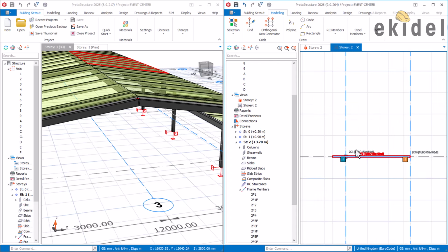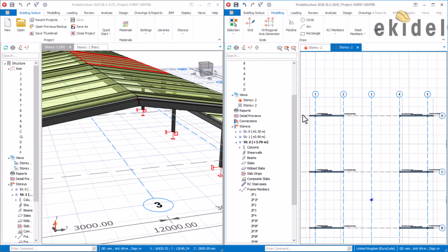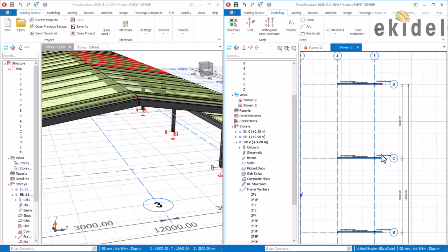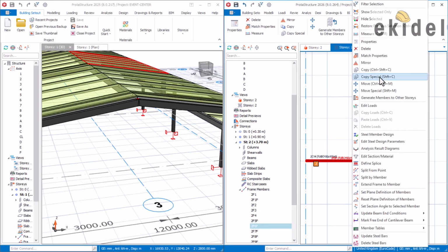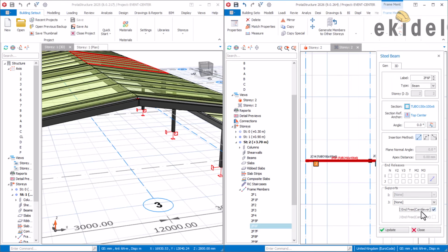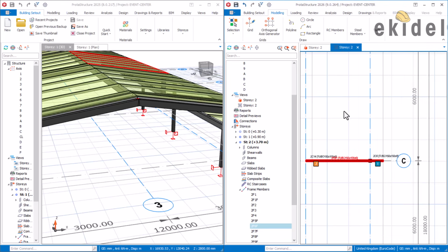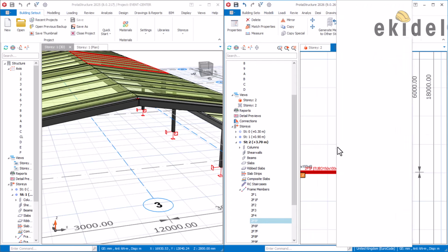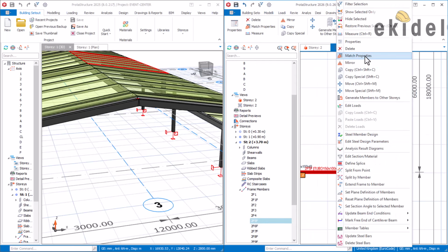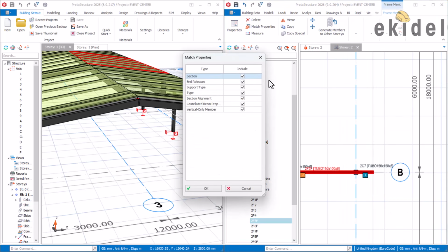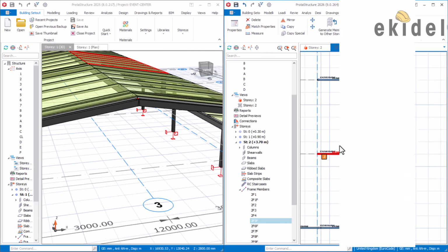Do the same thing for other beams. So I've done all these sides. I'll do the same thing now for this side too. Click here, right click here, properties. So it's to do the same thing by assigning cantilever at the I end, because the I end is free. Why not the J end? There's a connection there. We just make it free, because the short columns and that beam being welded together made that place a system and not a cantilever end.